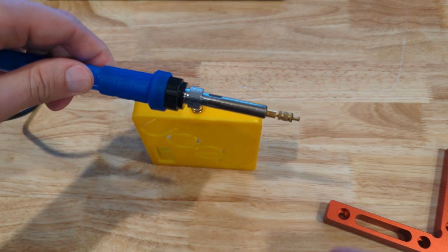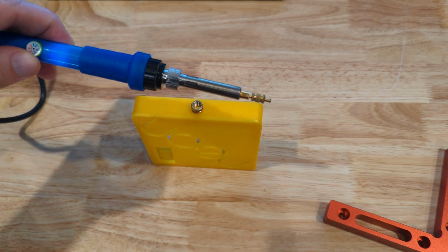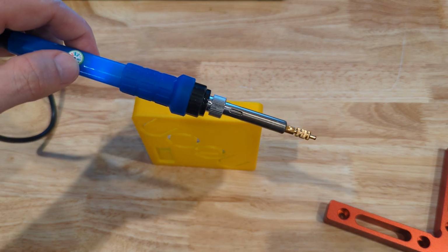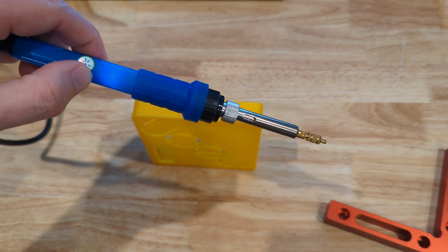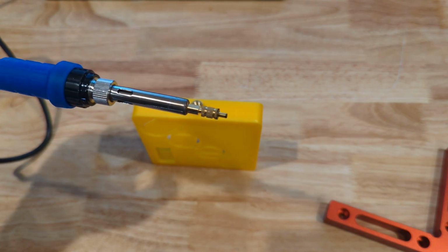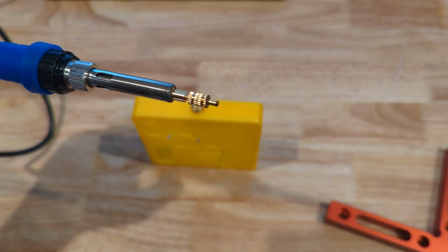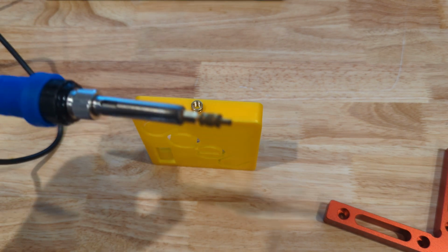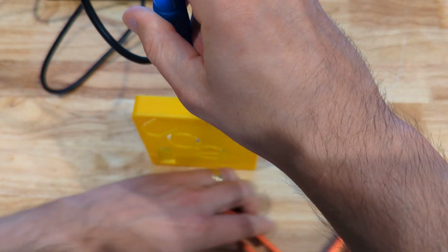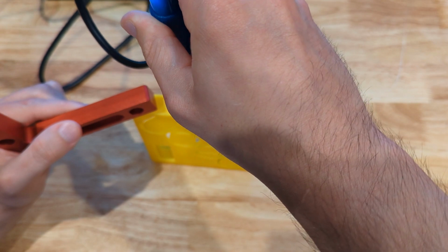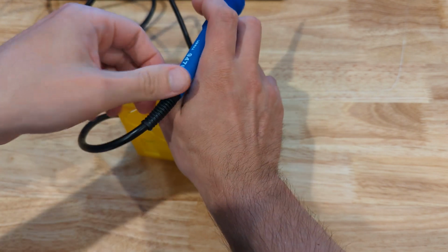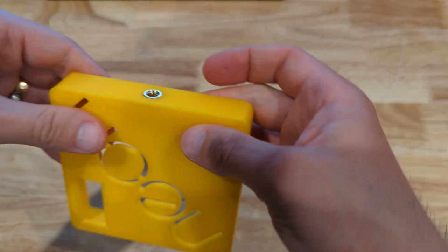I have a very simple soldering iron that I really only use for heatset inserts. I put it at the lowest temperature I can get. I don't want to melt too much of the plastic, really only at that point, and I don't want to deform any plastic and maybe get it in at the wrong angle. So this is meant for M3s, if I remember correctly. So that's not quite what we have here. We'll see how we go. All right, that worked somewhat.